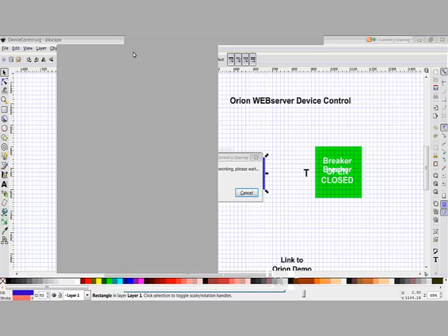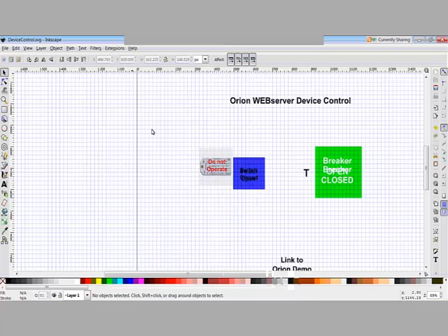But there's a control point that has been selected from your control outputs. And what it says is that that element is a controllable element. And that's where you select that. You also can say, I want this square to turn different colors based upon different conditions. So that's where you show that. So now what I'm going to do is I'm going to go to NCD, and I'll show you how you set up your dialog in NCD.